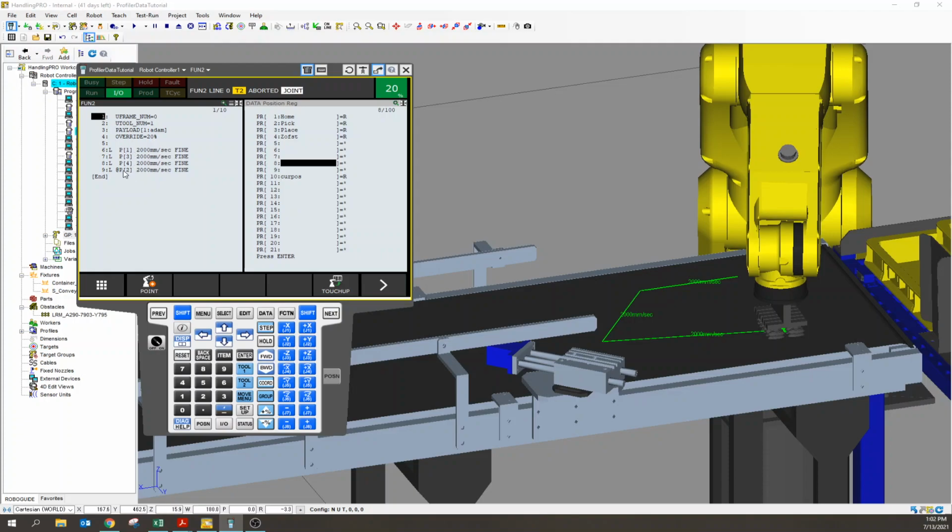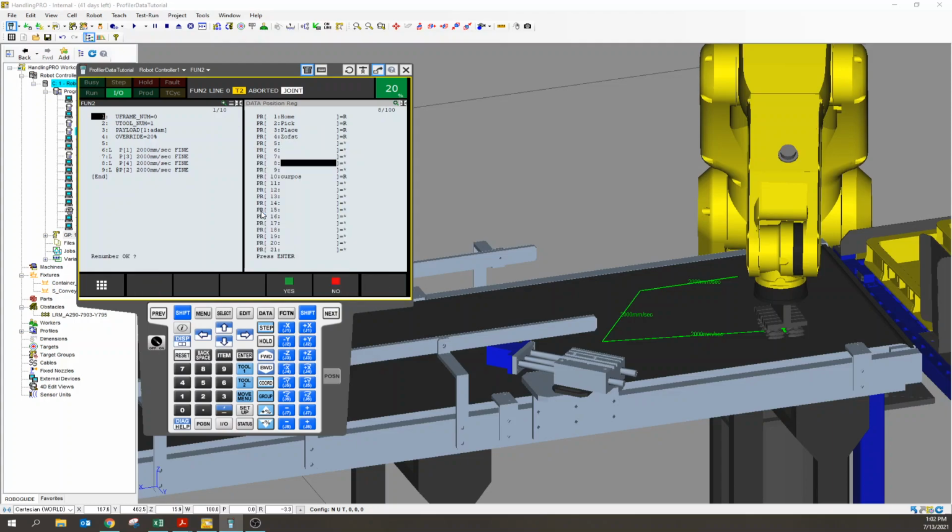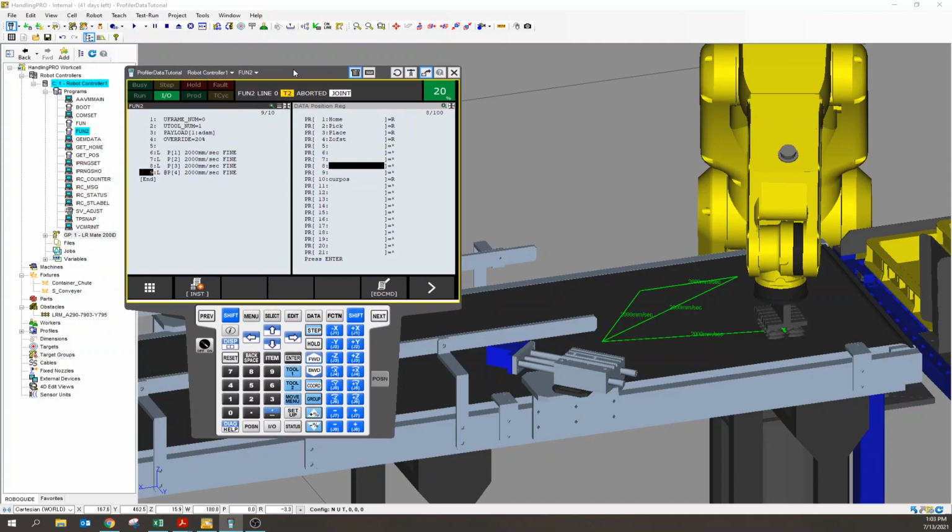So this is becoming a hot mess, and it's only 4 points. Imagine you had a whole program. It'd get ugly. So what do? Edit Command, renumber. If I want to renumber, it'll ask me, little love note, renumber okay? Yup. And look what happens first, ignore the lines for now, look what happens first to my code. My code goes to a 1, 2, 3, 4 in perfect sequence.